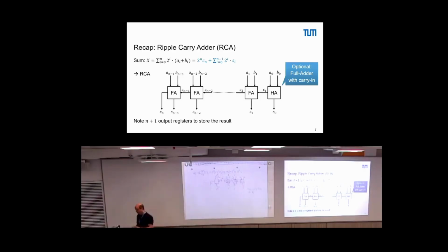Subtraction. One option is we implement a second circuit which has dedicated half subtractor, full subtractor circuits. Can be done. I think no one will do this in practice. What if we try to do this with a 2's complement? In 2's complement, if we want to do subtraction, we invert one number, add 1, right? And then we add it regularly.